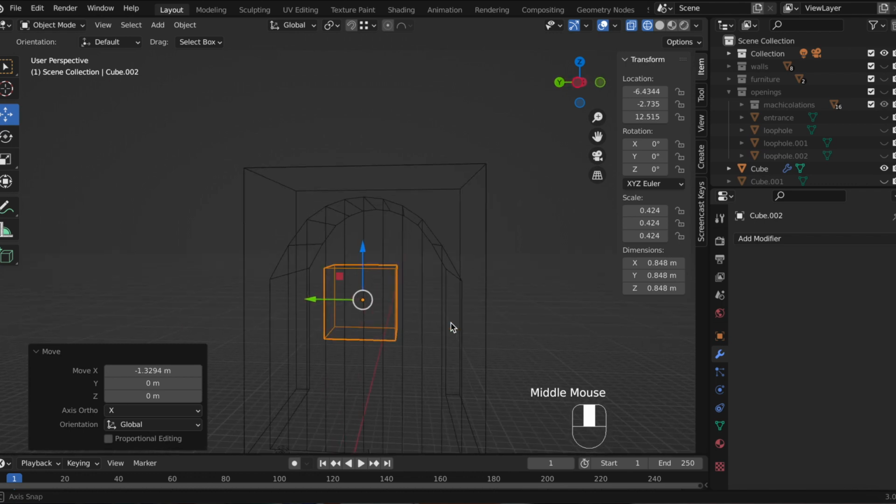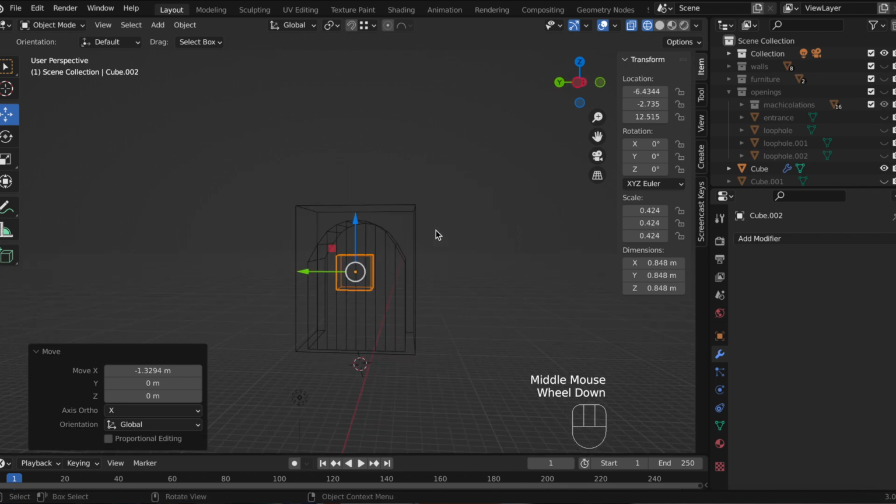One way we have often used to make holes or hollow elements is the Boolean modifier. However, as we have already seen, we can also use the inset tools and then join the edges of the two faces through the bridge. Now let us first try the Boolean and see if the result is satisfying.